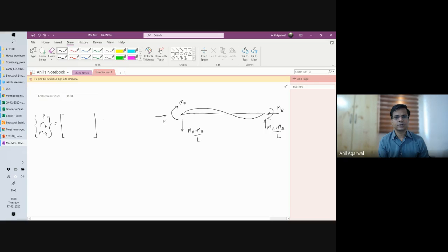This was a function of some kind of a stiffness, okay, E, theta A, theta B. And how were E, theta A, theta B defined? E is the axial deformation. Initially the member was this long up to here, and then it has shrunk to here. That is your E. Fine. And with respect to this line, which is the secant line, we will call it theta A. And with respect to this line, we'll call it theta B. Fine.